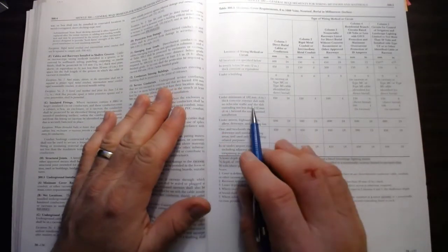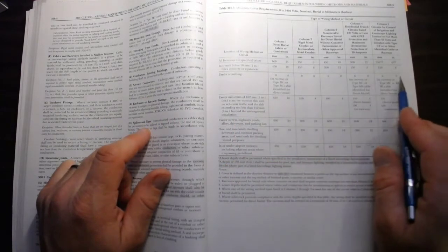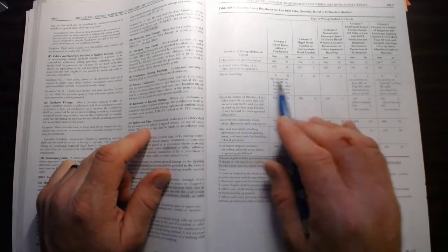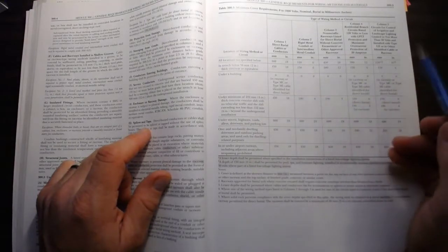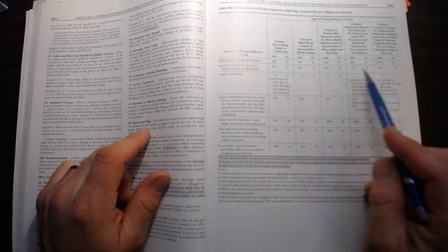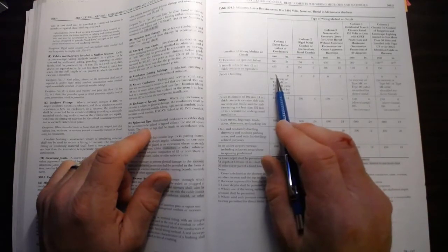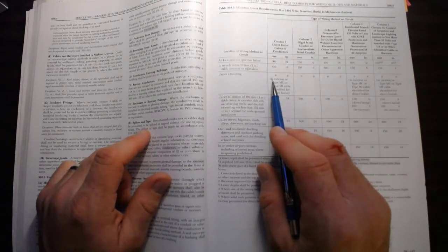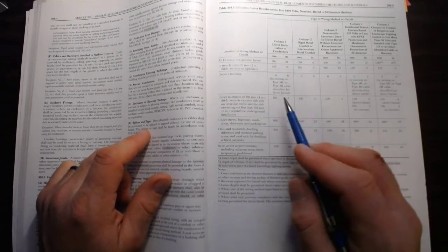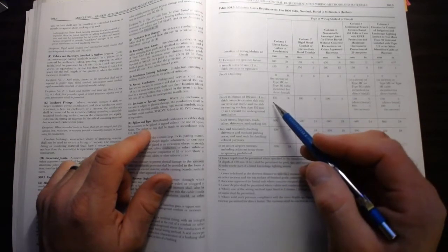For example, if it's under a building, all options are 0 inches. It can be directly buried right under the building. The idea is that we're protecting that conduit and we're protecting the conductor, especially if it's UF cable that's laid right in the ground or direct buried. Underneath a slab, it's protected. However, I would go a little deeper, because if they ever saw cut that in the future, you want to make sure you've got some distance from that saw cut.